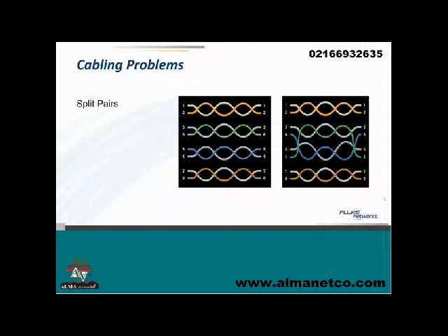It's very hard, the way that PoE works, to actually make it dangerous. It will only apply power if it sees certain electrical conditions at the far end of the cable, which your body or your tongue cannot provide. And if those conditions go away, the power will shut off. So it's actually very safe.